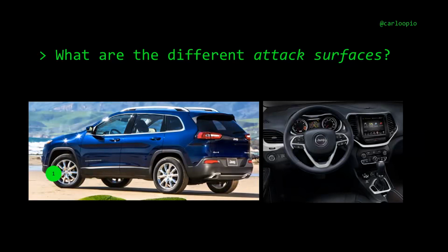In every car nowadays, you have to have a sensor that connects to the car, and it's located in each one of the 4 tires. That sensor measures pressure. The way it communicates to the body control module is via a radio signal. It's a low frequency radio signal that sends the data back to the module. So you can actually intercept that signal, and that would be one attack surface.